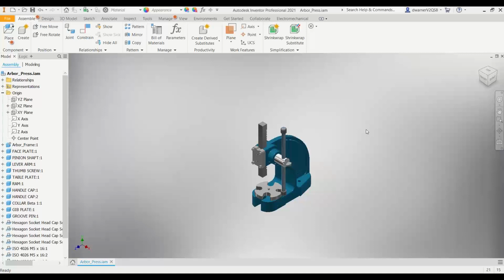what was happening is the design assistant was open in the background, and it's really a no-no to have it open while you're trying to launch Inventor. But I had to close it. The file is now open. The assembly file is now open, and you can kind of see through the browser that there is the collar beta 1. So again, it's a nice tool that allows you to manipulate and make changes, make complete copies, rename, all kinds of different things you can do in there. Definitely want to check that out. May make your life a little easier in managing your files.